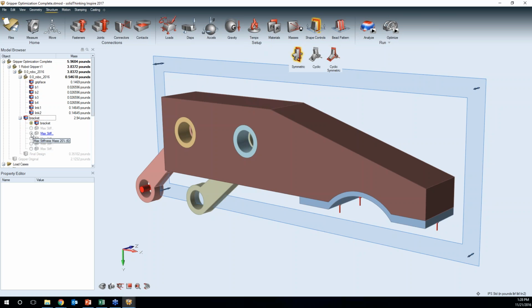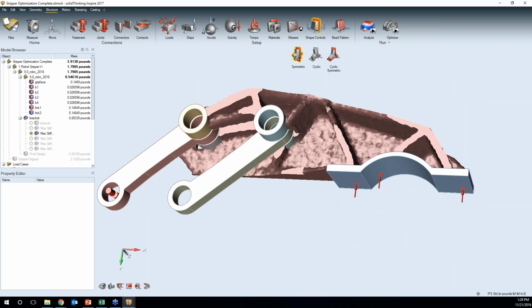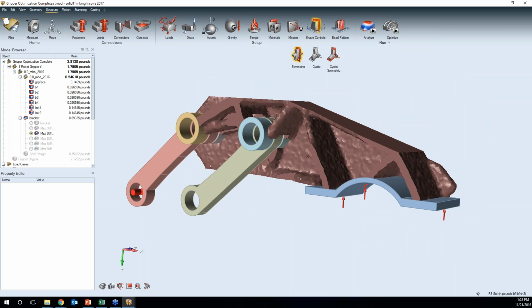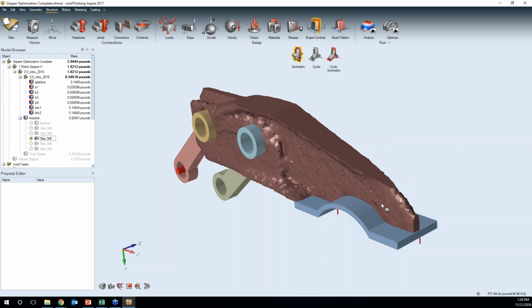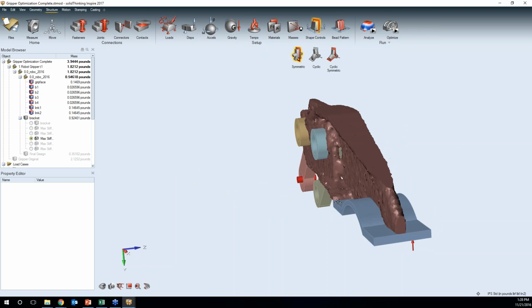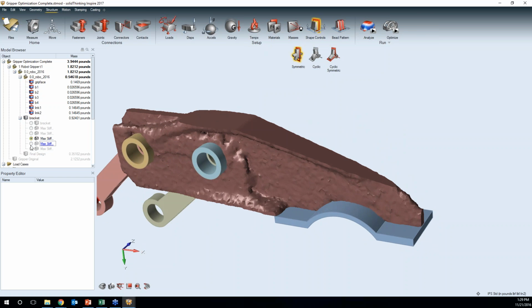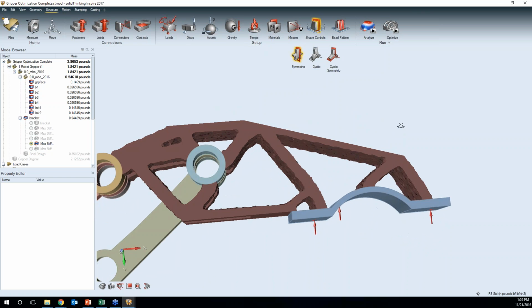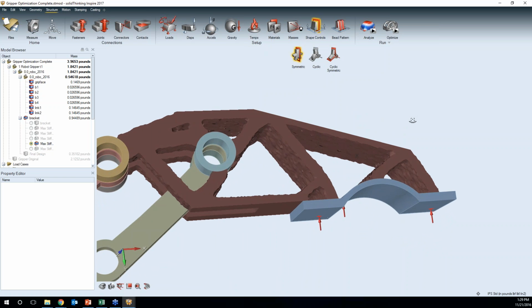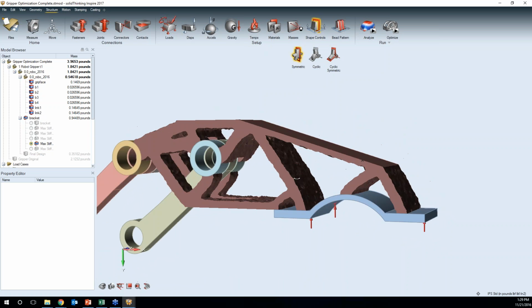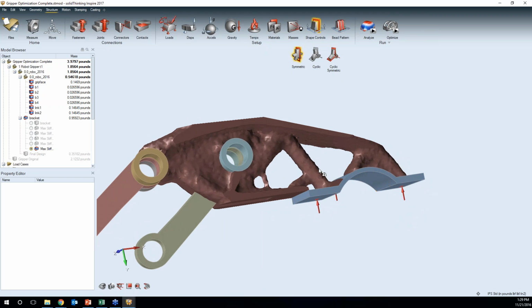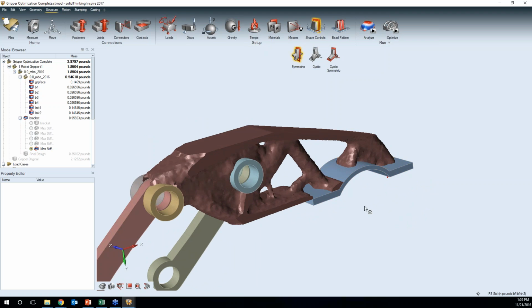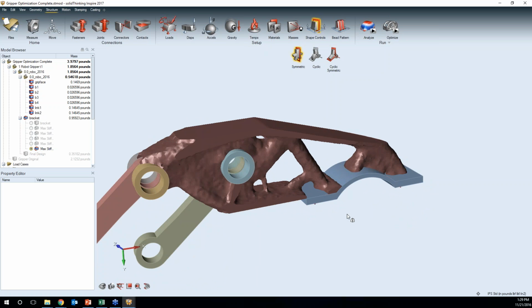If you look at how these different shape controls would affect that result, I can see here this would be the single draw cast design where I'm pulling a die from one side, versus a split draw cast design with no holes. Kind of looks like an alligator head, so more of an I-beam type design. To a water jetted cross section where I wanted a constant extrusion thickness. Again, all the same inputs, simply changing the design parameters. And here would be a more machinable design, something that you wanted to maybe mill out or do as a split draw casting. But you can see all these have the same inputs, simply a change in the manufacturing type.